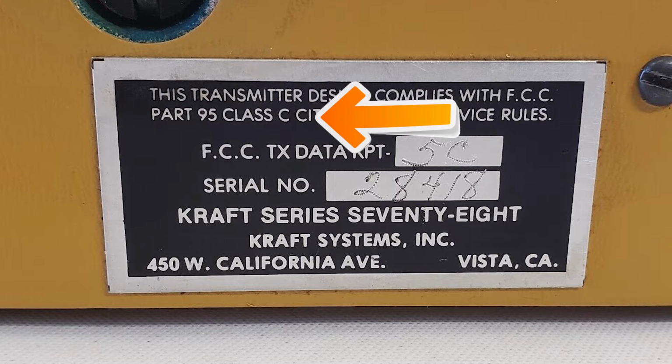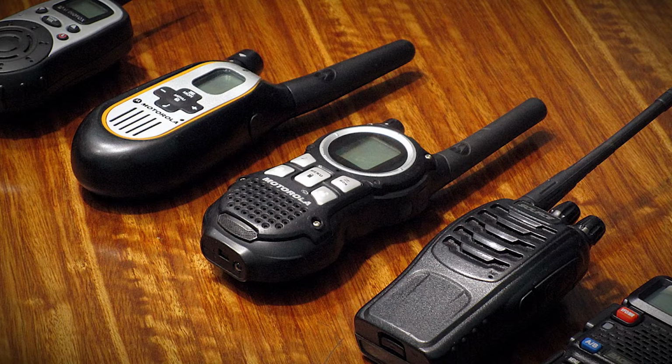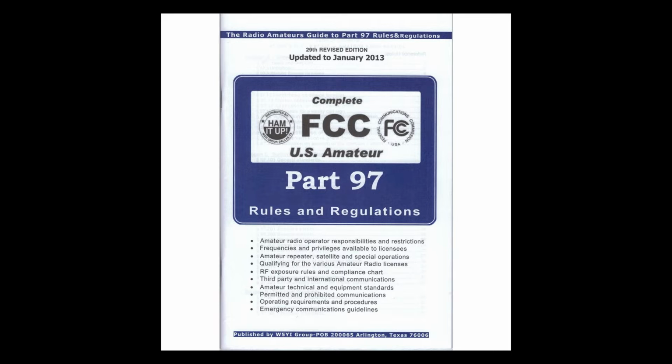General Mobile Radio Service Part 95 is a mixture of both. Most repeaters are wideband. The FRS channels are narrowband. Part 97, the amateur service, you can do either way, whatever you want. The vast majority of systems are wideband, although there are a few in various areas across the country that are narrowband, but the vast majority wideband. We're going to focus on wideband as far as these levels are concerned, and just remember, if you're doing a narrowband system, the levels are half of that.